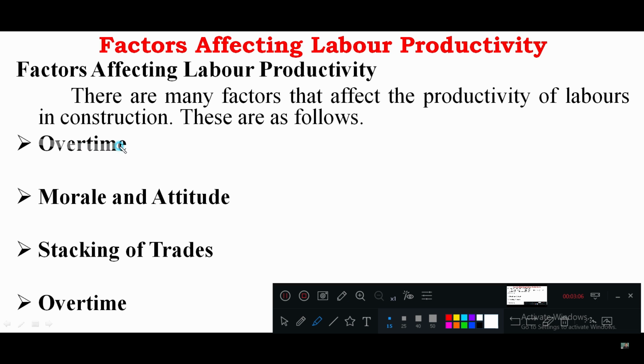We have finished overtime, and now it's morale and attitude. Here, the spirit of workers is based on willingness, confidence, discipline and cheerfulness to perform work or tasks. It can be lowered by a variety of issues, including increased conflicts, disputes, excessive hazards, overtime, over inspection, multiple contract changes, disruption of work rhythm, poor site conditions, absenteeism, unkempt workplace, and so on.